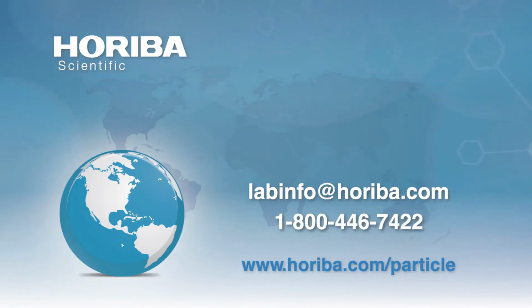And so you have to know when you're trying to understand agglomeration and flocking versus primary particles, you have to first of all define what you're interested in knowing. Are you interested in knowing the primary particle size? To some people, primary particle size means something that is like early on in the creation of the particle, but you can't actually ever see it again. A lot of people talk about aggregates, which are the smallest things you can break down to.